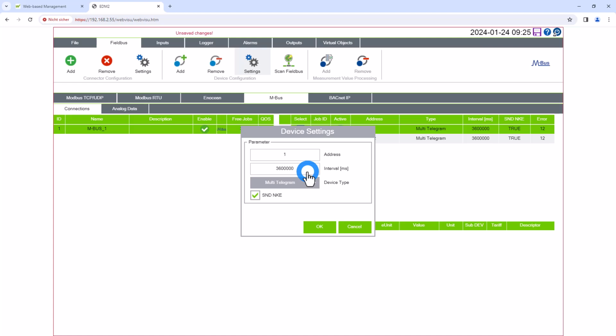So every MBus meter has its own memory, where the consumption is recorded, and you normally just have to take the values every hour, or it depends on your needs. Don't do that too often. For example, if you have an MBus meter for heat, there is a small battery inside for energy consumption of this meter, and it could be possible that if you read the value very often, the battery is low very quickly. In my case, I have meters with a power connection, so I can use 5 seconds.